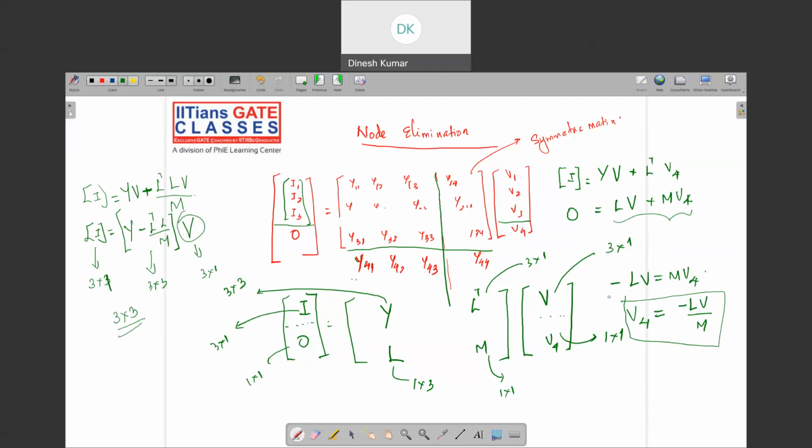So that means if we have a 10,000 or 12,000 bus system, in this only 6,000 buses are having some kind of a current source, right? So from a linear algebra perspective, A inverse into B will be the most computationally expensive. So instead of solving 12,000 cross 12,000, we can easily solve a 6,000 cross 6,000, and with each solution we can back substitute and find this particular value of voltage. That means the computation is now seriously reduced, right, by this particular node.